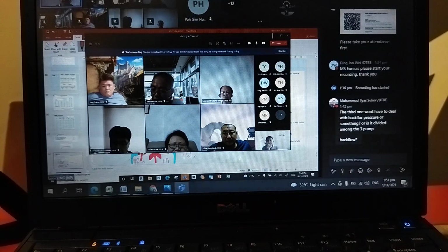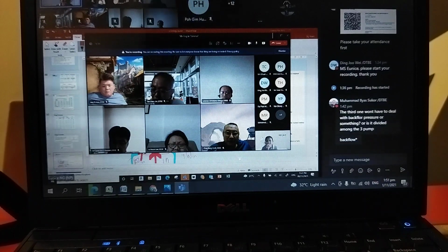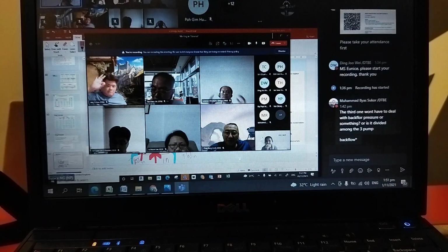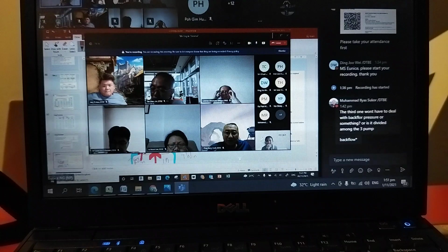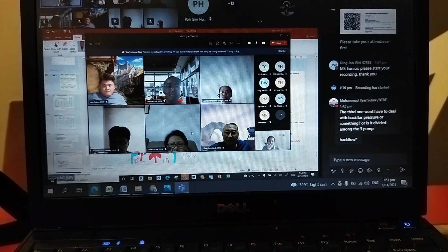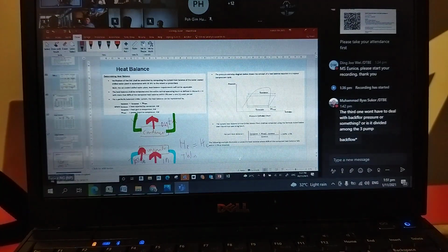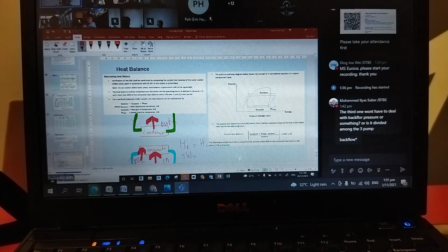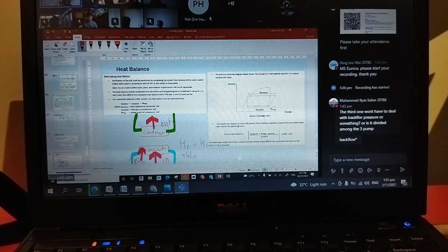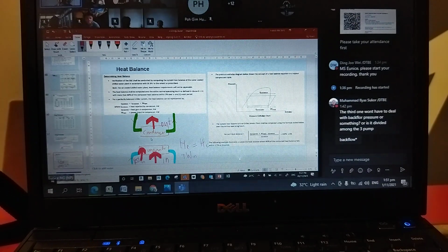So that's why Mr. Ang that day asked me, hey, there's a minus value, is it correct or not? I said yes, it's correct. Because if you look at the equation, this plus this minus this equals 100, it will be positive. But if it becomes negative, it means that the condenser is rejecting more heat than it can receive, maybe due to some error.